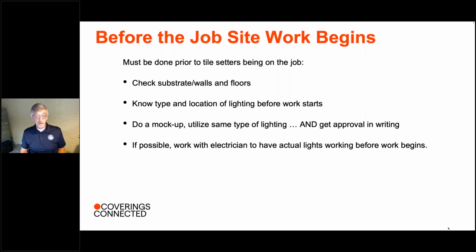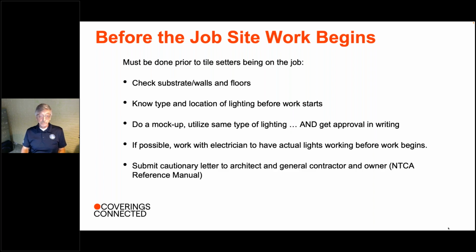When it comes to critical lighting, if ever possible, get the actual lighting installed before the work begins. See if you can get the electrician in there. See if you can get those lights installed. I'm going to show you some examples of how that will help you have a great finished installation.